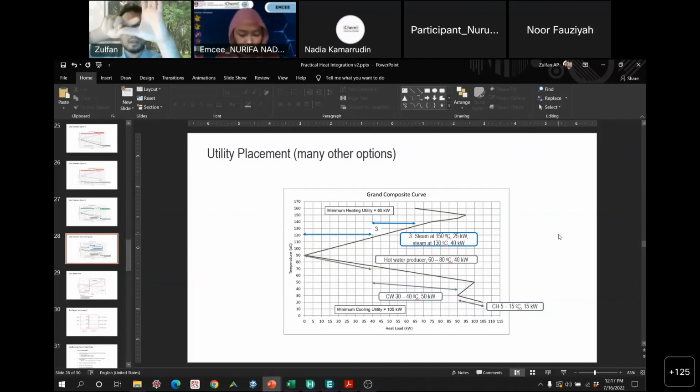That means the hot fluid on the wall is going to be sticking on the wall. So it will give you an additional layer of fouling. The more viscous the fluid on the hot part, and the higher the temperature difference between the hot and the cold, the thicker the fouling layer will be. If we have a thicker fouling layer, we will reduce the heat transfer from the hot to the cold. So that is another implication if we have too high a temperature difference.